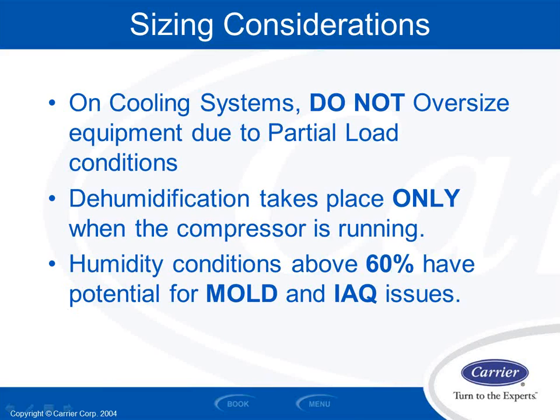But to answer your question, whether it's residential or commercial, the biggest step to correctly dehumidifying the space is to put in correctly sized equipment that is not oversized, meaning no safety factors. And for 50 years, we've added safety factors to our load calcs, we meaning an industry.